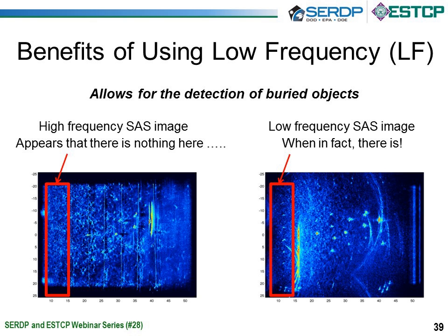You can see there's a bright set of noise at about 15 meters. This is not actually a target. This is an artifact of the fact that the research vessel was behind the rail, and there was a main lobe for the receiver that pointed out in that direction. So you can ignore that artifact, but you can see that it's almost trivial to identify the location of the rest of the scatterers in the scene because of the brightness and the contrast with which the targets show up relative to the background.